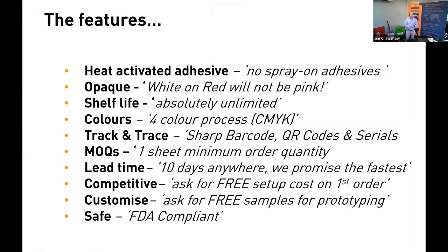Right, so let me just run through the features then on the post-mold graphics. As I mentioned, they are pre-coated with adhesive, so there's no spray adhesives required. That heat-activated adhesive is really just to hold it in place on the part while we run through that burnishing process. Those adhesives are not designed to glue it to the part. When we oxidize the surface of the plastic, it opens up the pores. When it returns to normal, it grabs the graphic and takes it with it.